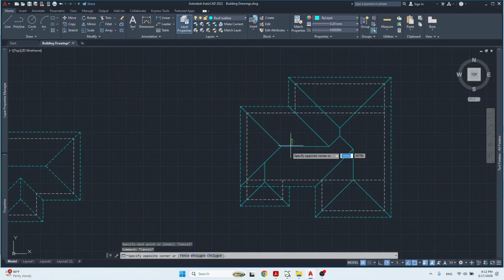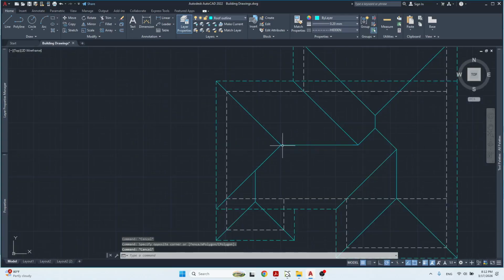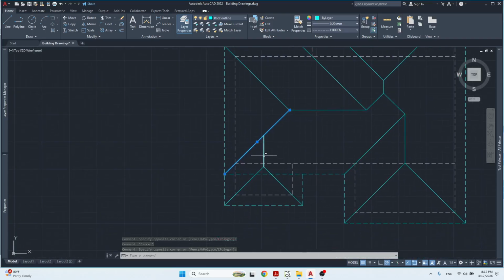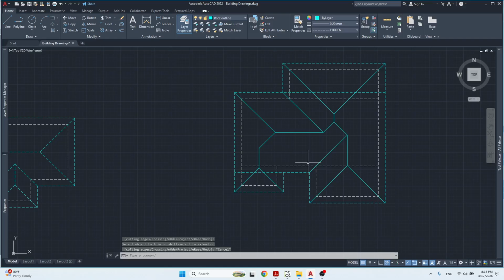So remember, we have a ridge, and then there's this hip rafter coming down, and this hip rafter over here is coming down, but as it's coming down, it meets the ridge of another part of the roof. It meets another ridge. So what do we do when we see another ridge? It stops. This hip rafter stops when it gets to that ridge. So we could get rid of this side.